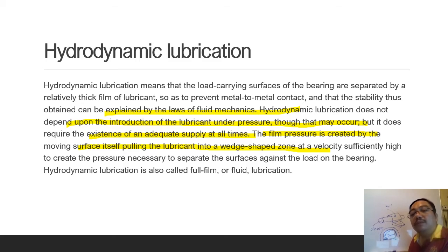So we want to avoid metal to metal contact. This is why it is called hydrodynamic lubrication, meaning that all the time the oil supply, the lubrication supply, is constant.